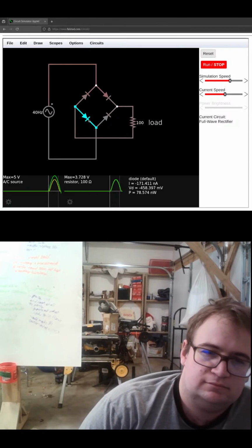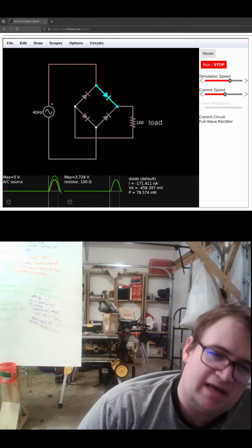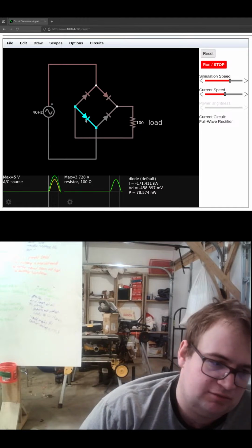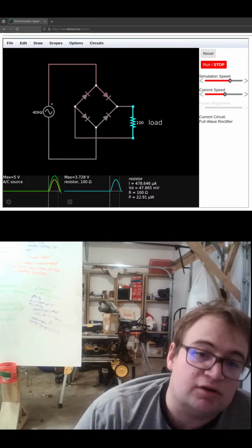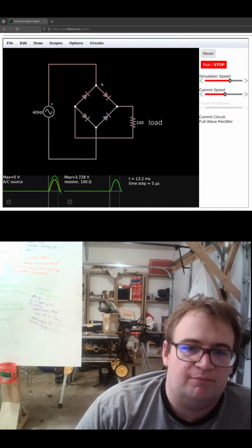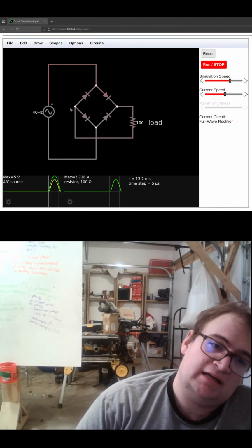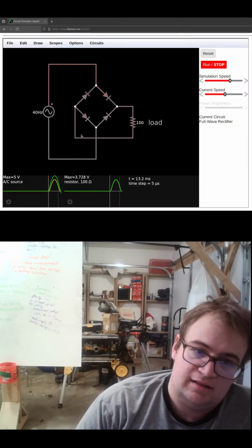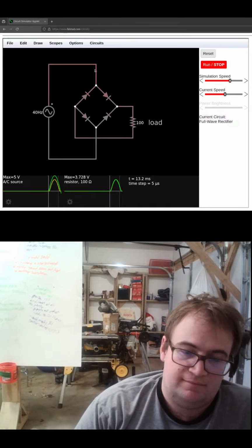Let me see if that's right. So, but yeah, no, we'll have a diode drop here, then another diode drop here. So actually, we're going to lose about 1.2 volts there. So this is only going to be like 3.8 volts, maybe 4 volts. Now let's say if we have a minus 5 volts here. Well, then we're actually going to conduct through this way, then through the load, and then back out this way.